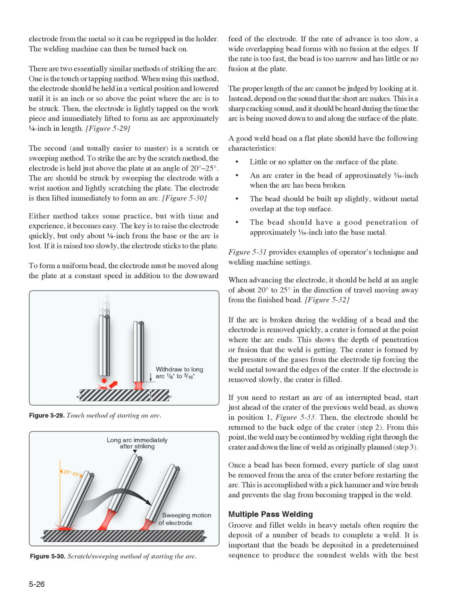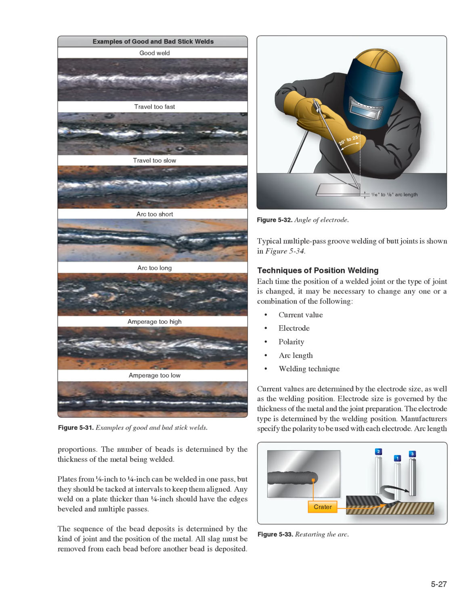Multiple pass welding: groove and fillet welds in heavy metals often require the deposit of a number of beads to complete a weld. It is important that the beads be deposited in a predetermined sequence to produce the soundest welds with the best proportions. The number of beads is determined by the thickness of the metal being welded.